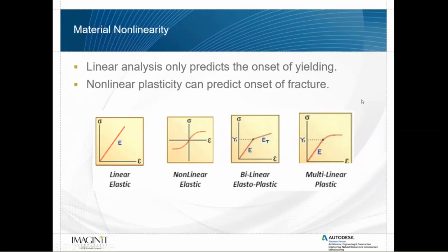So anytime you're looking at nonlinear plasticity, so you're looking at permanent deformation in your models, you'll need to reclassify your material and add in some additional information for the solver to use.